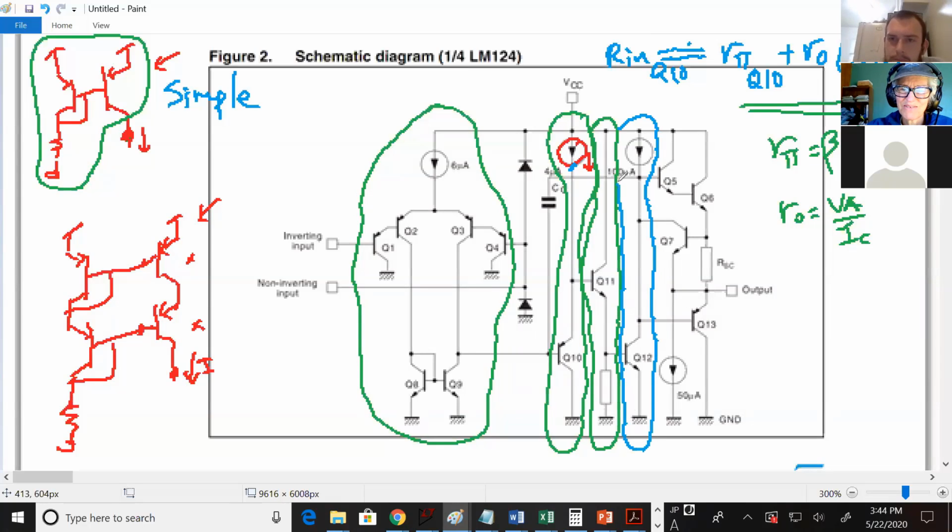Okay. Yeah, so that's a common emitter. And when you see the current source, again, it's this circuit over here. And so what's up here is actually a PNP. So you've got NPN here and a PNP. So what flavor of common emitter is that? You're saying that the current source is a PNP? Yeah, let's say it's a simple current source. An active load. Yeah. Exactly, that's what it's going to be. So this is a CE with active load.